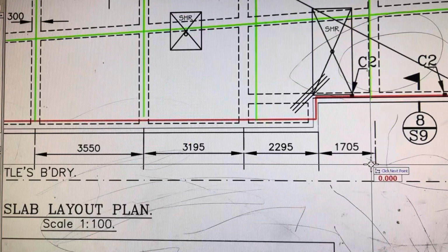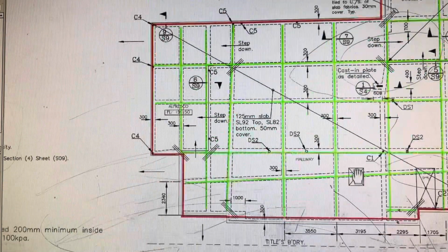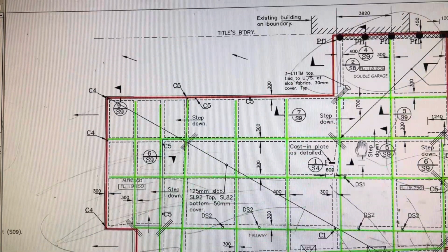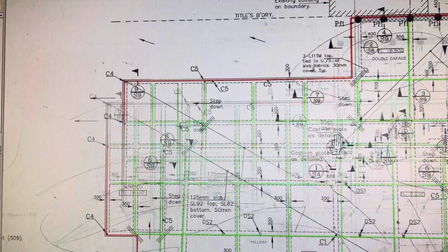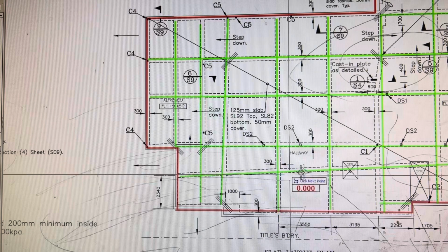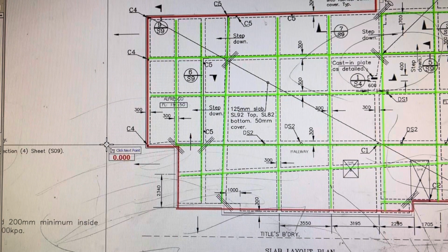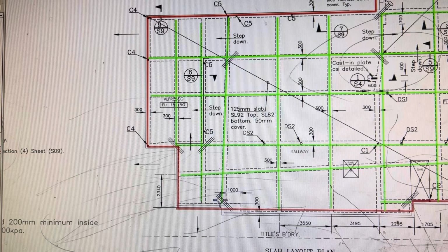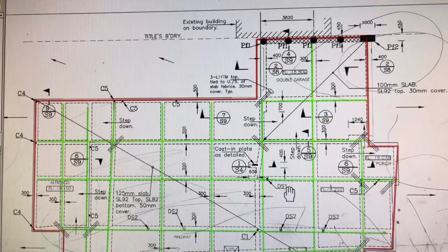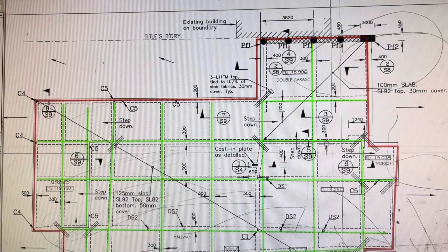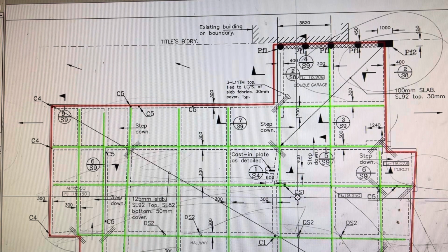Upon checking, we just found that we missed this horizontal, so now we can cover it. Here you're getting the full quantities of all external beams and internal beams which will support this raft slab. It's also called a conventional slab. We can right click and stop. So we got these quantities. Based on these quantities, we can estimate how much this slab will cost, what are the quantities we require to build this slab.